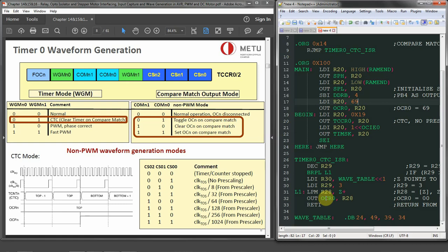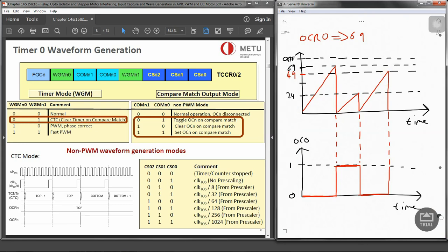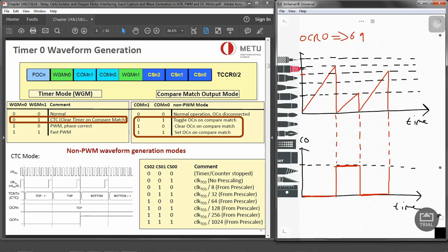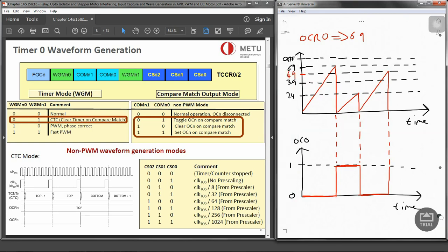And also, this will actually generate a new interrupt. So we'll go back, and that will be 1 now. And we will get the second, third value, which is 39. So we have to plot that 39. That was 49 and now 39. I've got dotted lines. That means our timer is going to go up to 39 and then down, and this will carry on generating the wave.